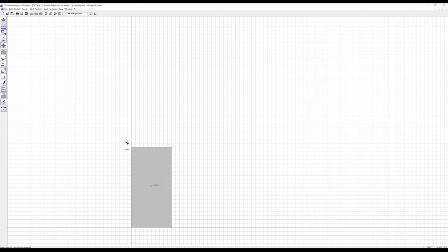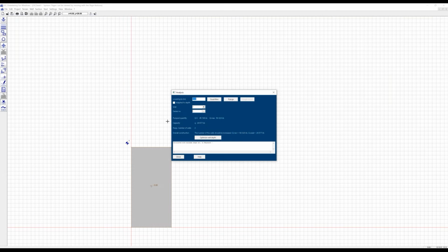Now we can make a first calculation over this analysis dialog. And it is important that this is first only a rough estimation, because we calculate the capacity of this well, which has quite a large range or reach. But if we have several wells, which might be very close to each other, then one well will take water from the other, so they influence each other.